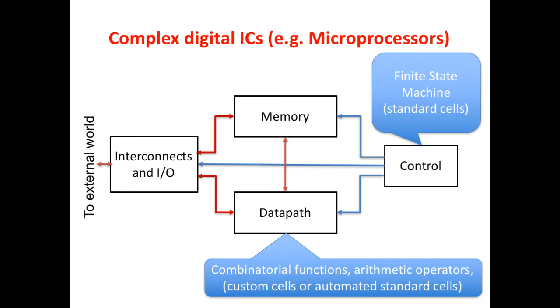Standard cells are reusable logic gates and single registers or single blocks of registers that can be used as a standard building block of a combinatorial circuit of a finite state machine, so that each block is designed only once and then it is used in different types of more complex circuits.